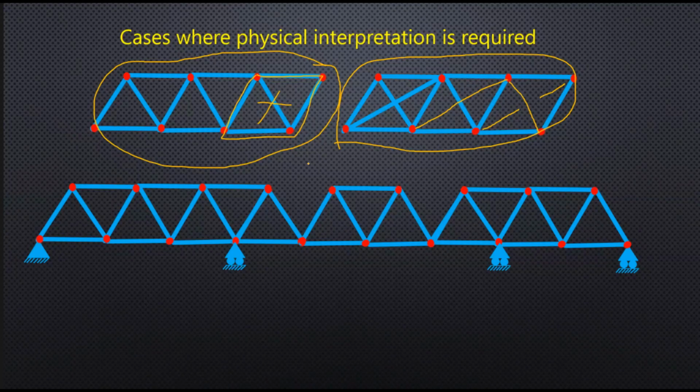But in the case of indeterminate truss systems, with the failure of one or two members, of course you have to ask how, there is a path of redundancy. So what I want to teach the young people is that usually the members added to the system are primarily to give the force flow path.